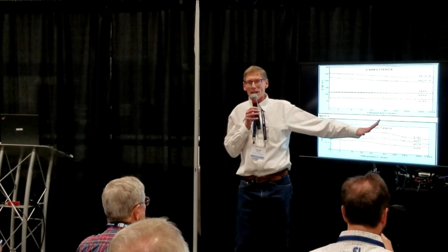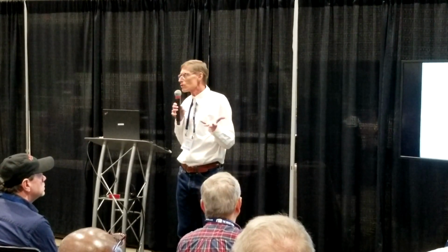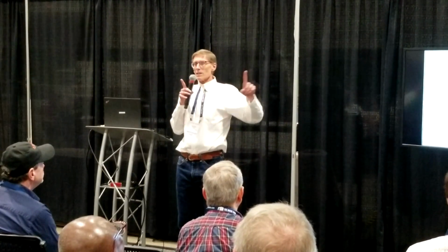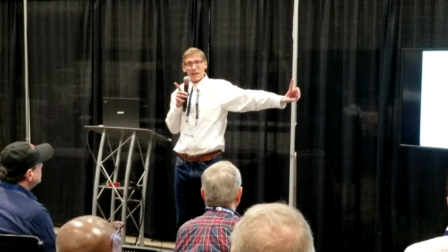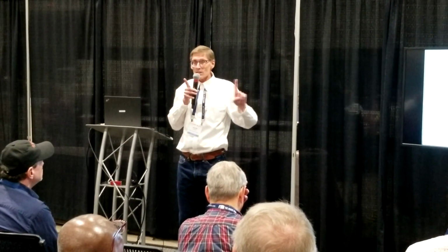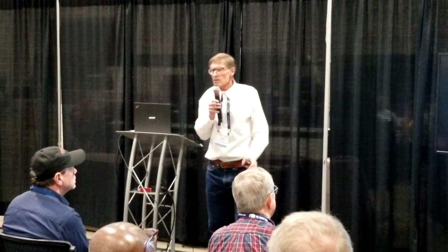What actually is happening is the skin effect is predominantly starting to influence the inductance measurement, believe it or not. How can that possibly be? Because what's inductance determined by? How close two conductors are together. It's called loop area. So if my conductors are real far apart, I have a very high inductance cable, a lot of loop area. As I bring those conductors closer and closer together, the loop area gets smaller, my inductance goes down. And you look at it and you say, well, Galen, you're not bringing those conductors together, they're just sitting there during the measurement, so why is it dropping?